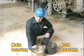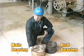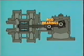Compressors have main bearings and rod bearings. Main bearings support the crankshaft at the center line of the frame. Rod bearings, located at each end of the connecting rod, allow the rod to rotate smoothly with the motion of the crankshaft. Both main and rod bearings are types of sleeve bearings. Once again, lubrication is vital. In fact, lubrication must be continuous to keep friction minimized.